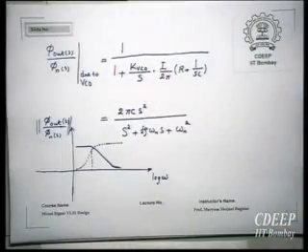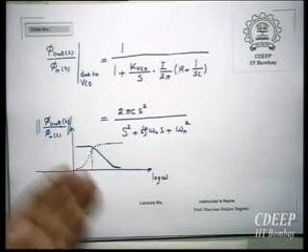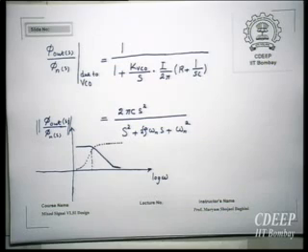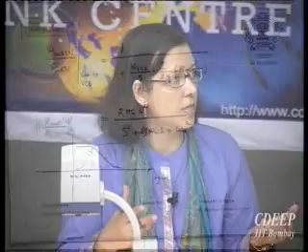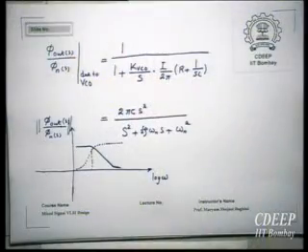But at the same time, low frequency jitter from the reference will come through. And second, we don't want the bandwidth of this filter to be very high, because we want to limit it to get proper locking. So this is again the same conflict that we have. This is one important thing, and we will see it is not limited to this.